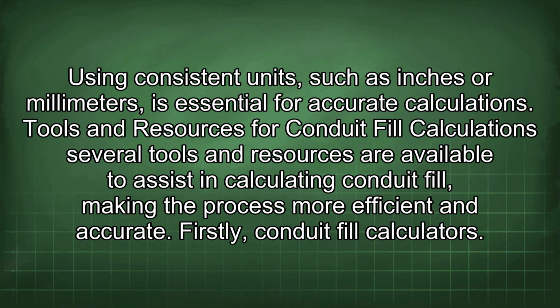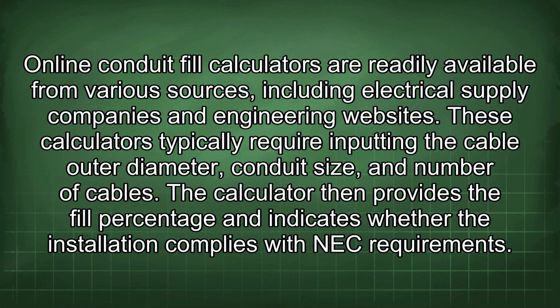Several tools and resources are available to assist in calculating conduit fill, making the process more efficient and accurate. Firstly, conduit fill calculators. Online conduit fill calculators are readily available from various sources, including electrical supply companies and engineering websites. These calculators typically require inputting the cable outer diameter, conduit size, and number of cables. The calculator then provides the fill percentage and indicates whether the installation complies with NEC requirements.